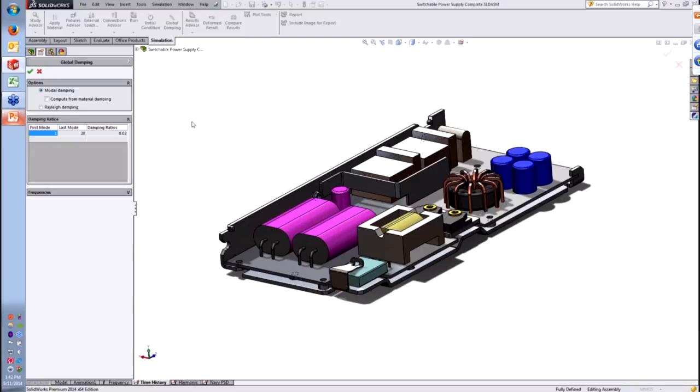So there's a lot of guidelines for what kind of damping ratio you should use. There's things like quality factors that you often will find in your mil spec. In this case, we specified 0.02, or roughly 2%. And that's going to be the damping ratio for all the different modes that might get excited. And again, those modes are something that the frequency analysis would find. You'd be able to specify different damping ratios at different modes if you needed to.